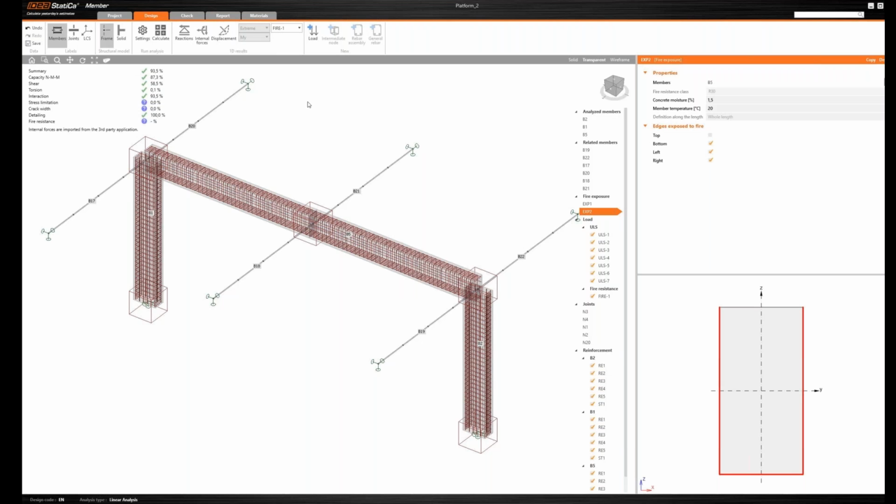Everything is green here. The applied reinforcement passes all checks. We have some question marks because I didn't import the SLS combination to check stress limitation and crack width, to save some time. However, all other checks were performed.